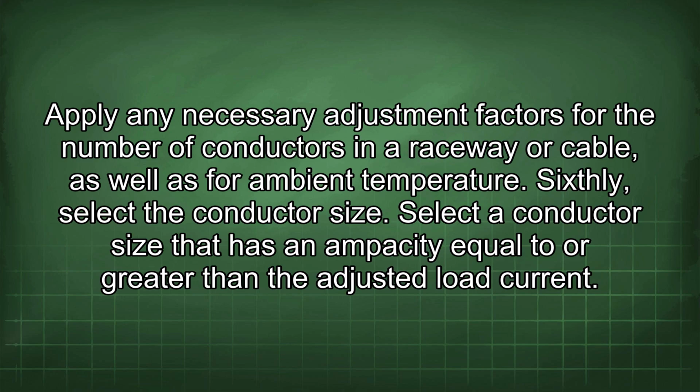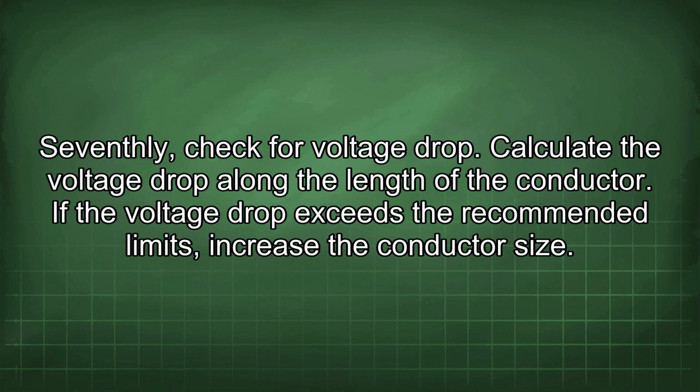Sixthly, select the conductor size. Select a conductor size that has an ampacity equal to or greater than the adjusted load current. Seventhly, check for voltage drop. Calculate the voltage drop along the length of the conductor. If the voltage drop exceeds the recommended limits, increase the conductor size.